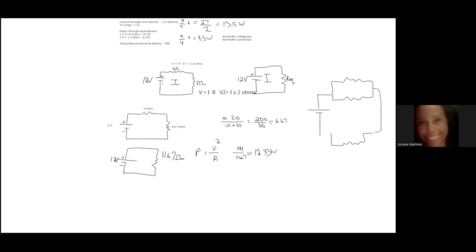Each parallel system would be simplified first using the formulas that we've worked with, and then you would have two series resistors after you replace the parallel systems, right? Whatever you end up getting here, this new value would become a series resistor with this new equivalent resistance here.